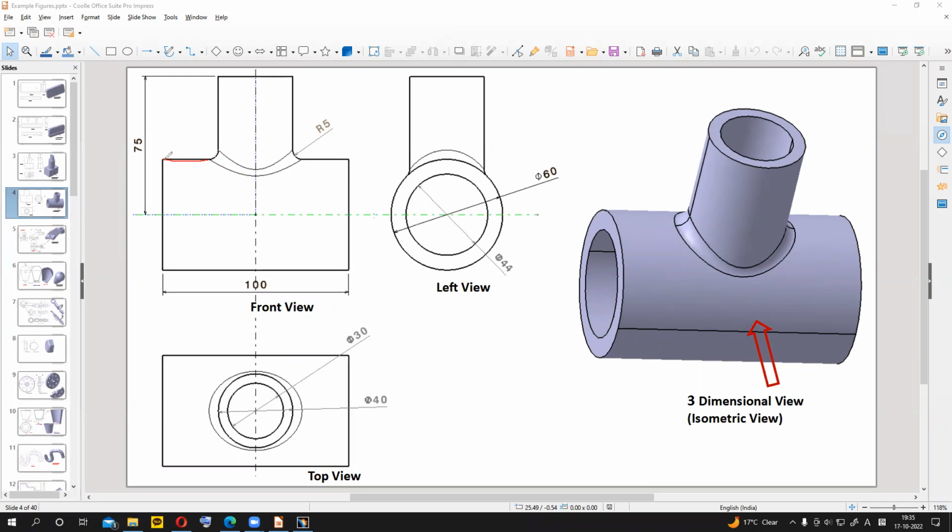if you consider this drawing and make it using pad, you will get this rectangular shape. So you will not get the cylindrical shape, so we cannot use this front view. What we have to do is make use of the left view, make two circles and pad.